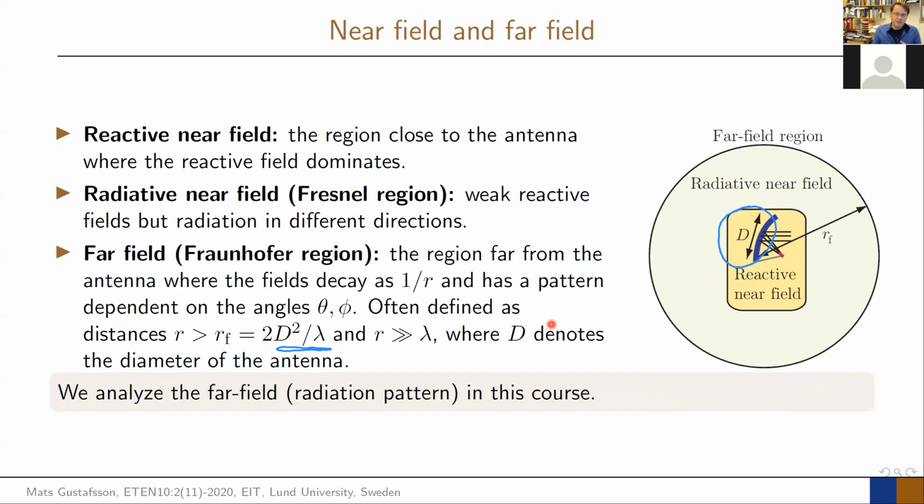And what that means is that the phase doesn't affect it in a very complicated way. It's a very simple way it affects it. And that simplifies a lot of the analysis, and it means that these quantities like the gain and the directivity are defined because they are far field quantities, and they only depend on the angle. So if I have this antenna, I get some radiation intensity there, there, there, and there. And it only depends on the angles. If I measure the angles from one piece, I get this value.